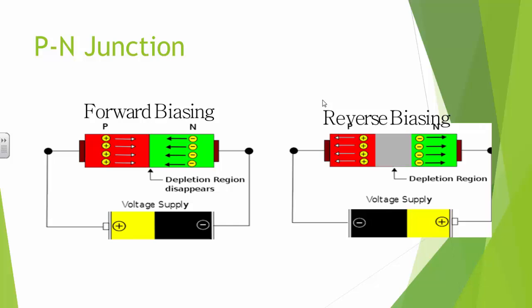And that PN junction, if we have a forward bias in which the negative potential is at the N side and the positive potential is at the P side, we see a system where electricity can be conducted. So electricity can flow. Our electrons flow from the negative terminal of the battery through the N-type semiconductor, and they move towards the holes on the P-type semiconductor, and they meet in the center. And this is great.